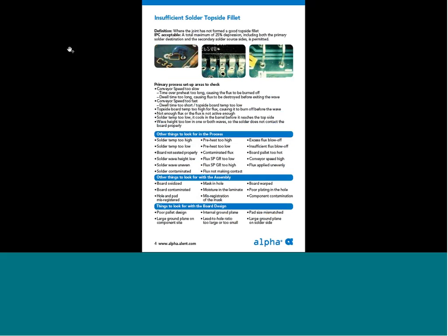Insufficient solder topside fillet. We're getting a lot of information about this and quite frankly concern from customers with the advent of lead-free processing. IPC says 50% hole fill is acceptable. A lot of customers don't like to do that. There's a few ways to look at this and try to solve it, up to and including doing your through hole during your SMT mounting process. I believe that's another webinar.